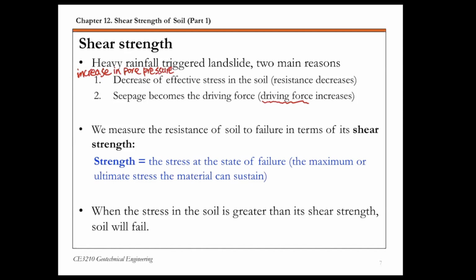Strength in general means the stress at the state of failure. So basically the maximum or the ultimate stress a material can sustain. That's the definition of strength. And in geotechnical engineering, we are more concerned with the shear strength and the shear stress, because for most geotechnical engineering problems, soils tend to fail due to an excessive amount of applied shear stress.